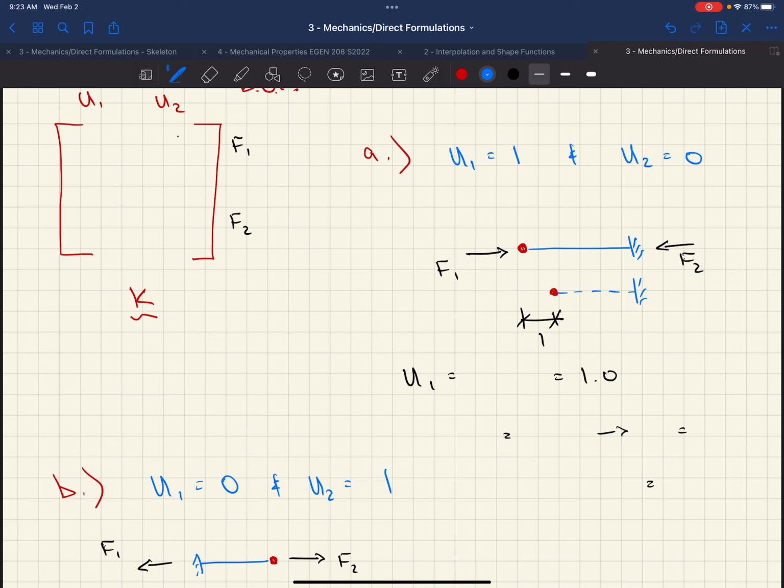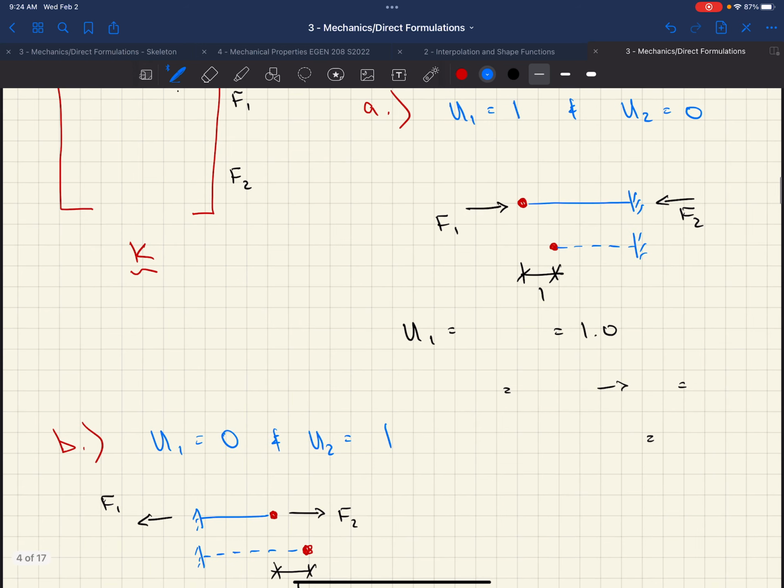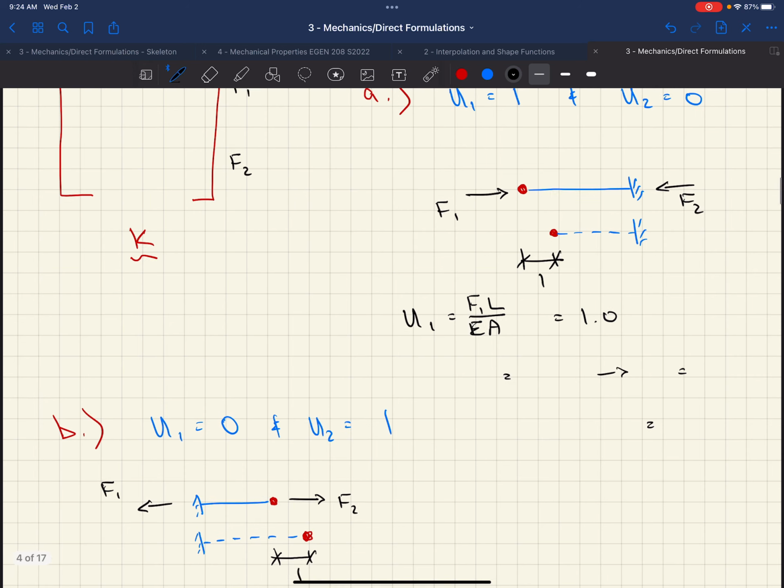All right, what's the displacement of the axially loaded bar? Just gave this to my sophomore class. It's the equation. So PL over AE. Well, in this case, we have force instead of P. It's F1 L. I'm doing EA. That's way better. If it's F, then it's F1 L over EA equals 1.